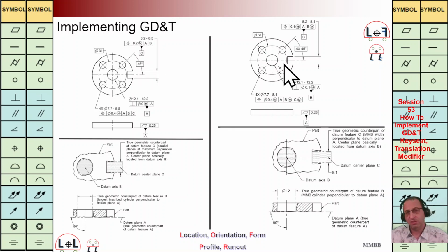But on the right hand side, what do we have here? We have a modifier for reference axis B for this hole. It means we have this possibility for shifting because we have B here, this hole. Whenever we have this MMC here, we should have the maximum material on that hole. That's why we are going to have the smallest gauge here, and for different sizes of the hole, we have this possibility to shift it. We have more freedom here.